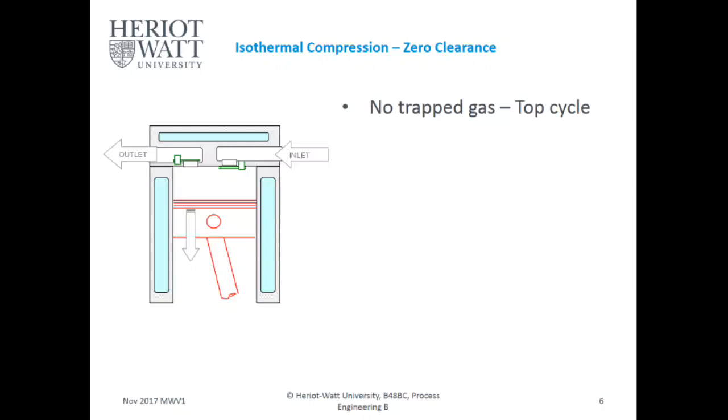So that means that no gas is trapped within the piston, and hence the inlet valve will open immediately as the piston moves down. So if there is no gas, as soon as you move down, the inlet valve opens. But in reality, the piston moves down, it creates a differential pressure, and it opens up. That is the difference between our ideal situation and reality. As soon as it moves down, it opens in our case. So B opens, piston down.